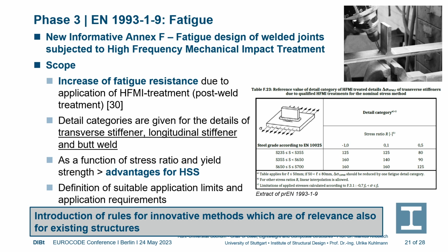We also added a new informative annex, fatigue design of welded joints subjected to high-frequency mechanical impact treatment. This HFMI treatment is a post-weld treatment which allowed to increase the fatigue strength really drastically.